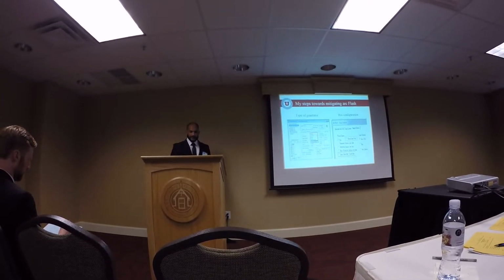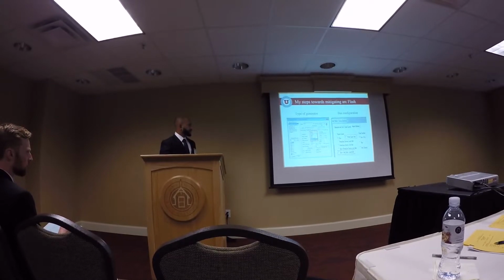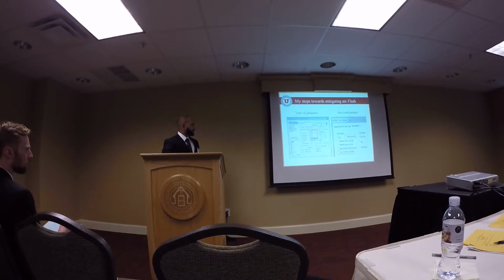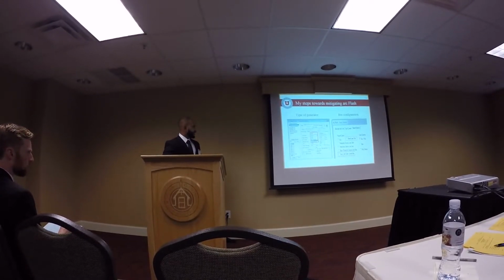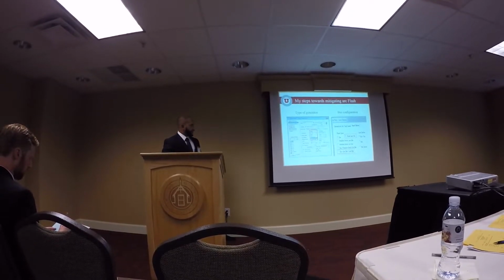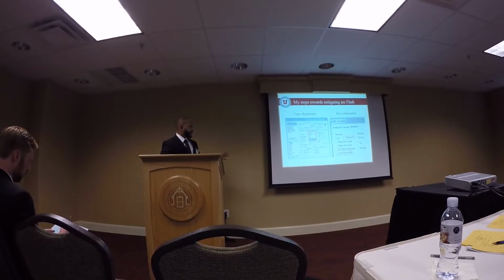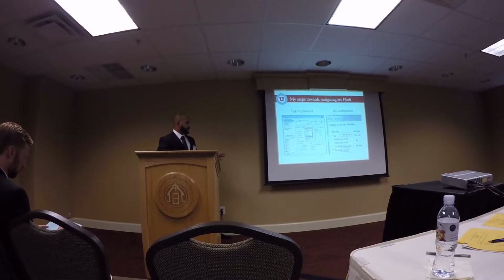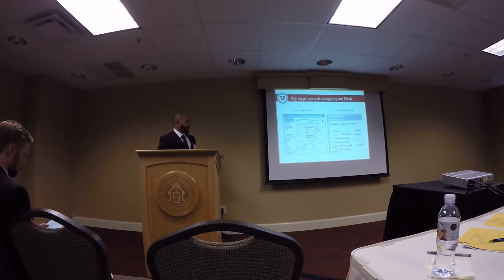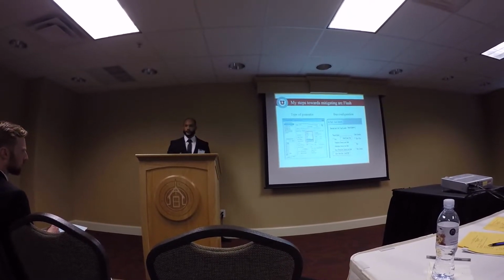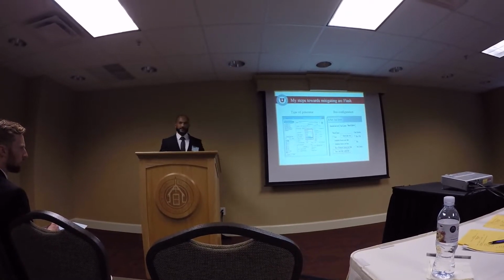The way I address SKM is, when I use the emergency side, I need to figure out what the primary generator being used is. Is it zigzag, Y-connected, delta Y-connected, or delta connected? Once I identify it and put it into SKM, I need to select whether it is bus side, line side, or load side. I ran it in bus side, line side, and load side, and took the worst case scenario. That way, if something happens, I know what's the worst that could happen,